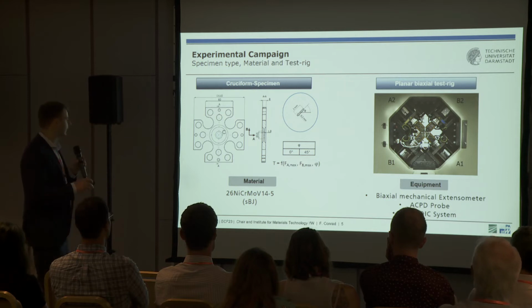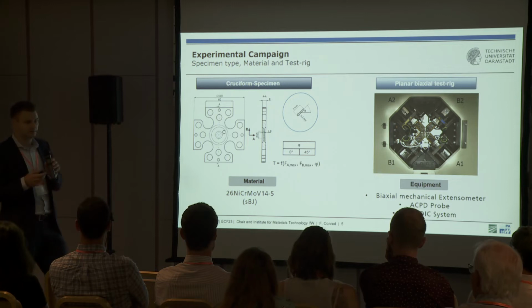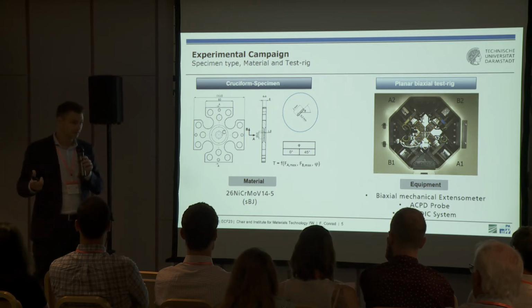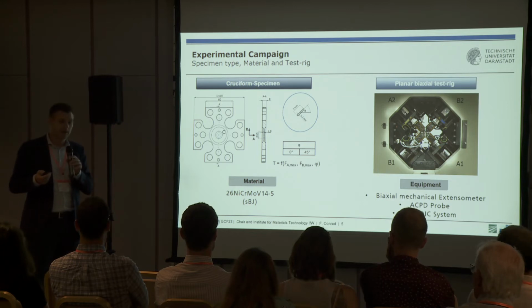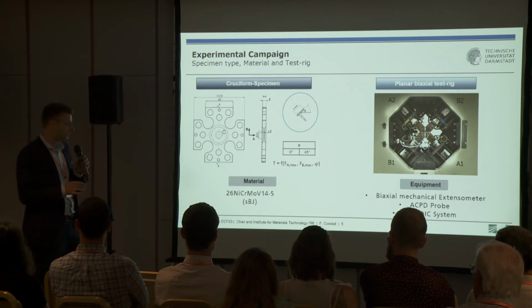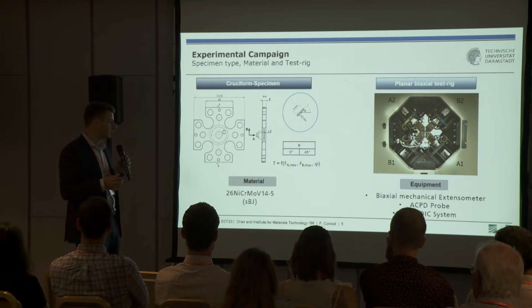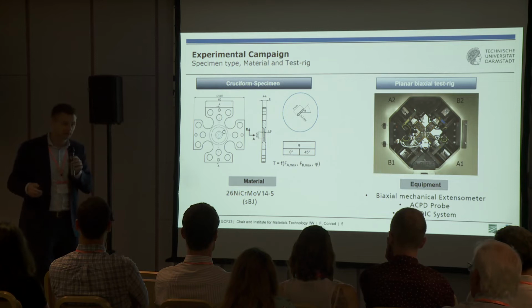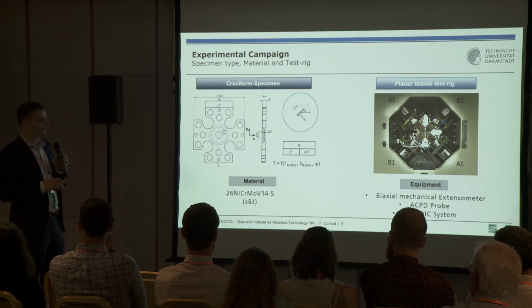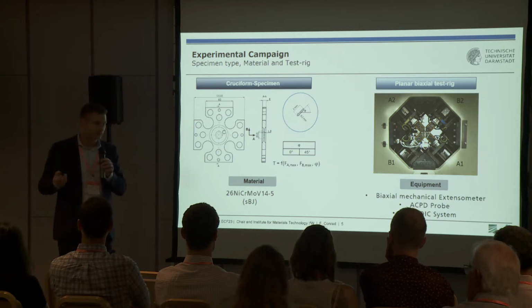As you can imagine, this test stand and the specimen allow a lot of investigations on fatigue crack growth. We were looking with constant amplitude loading at the influences of T-stress. We were looking at plasticity-induced crack closure. We were looking at influences of interspersed cycles, so overloads and underloads. And furthermore, we also carried out investigations about the crack growth direction and crack bifurcation.